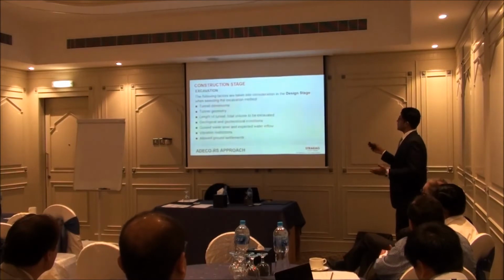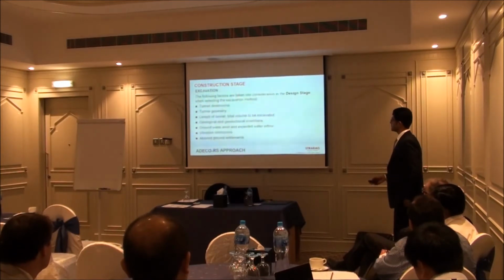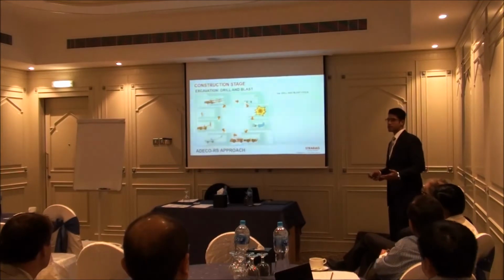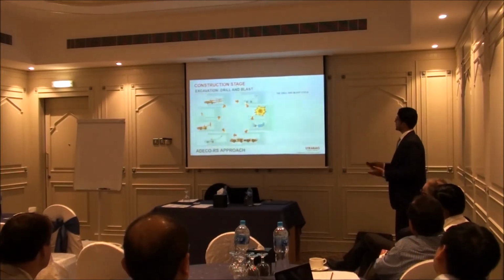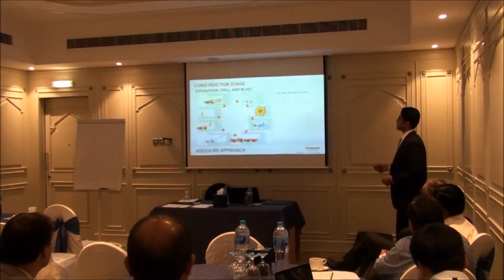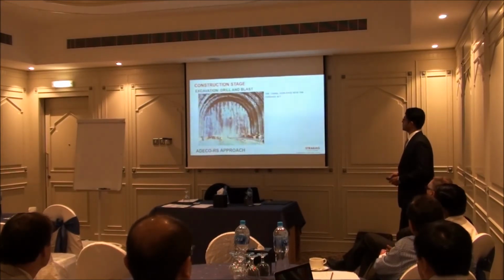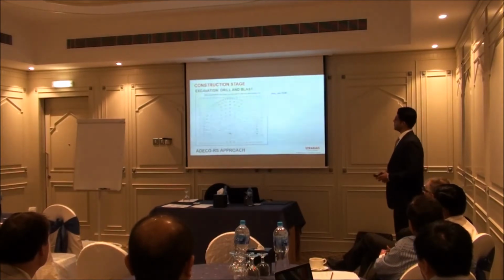There are several guidelines or parameters which need to be checked before an excavation method is used, but all of them are already decided in the design stage. So if the rock conditions are good, then we can employ the drill and blast technique. A typical drill and blast cycle is shown with drilling and then charging, blasting and defuming, mucking out, then chipping any loose rocks and rock bolting, finally surveying, and the cycle starts over. This is how a tunnel face would look where the charges are set. A typical drill pattern is shown.